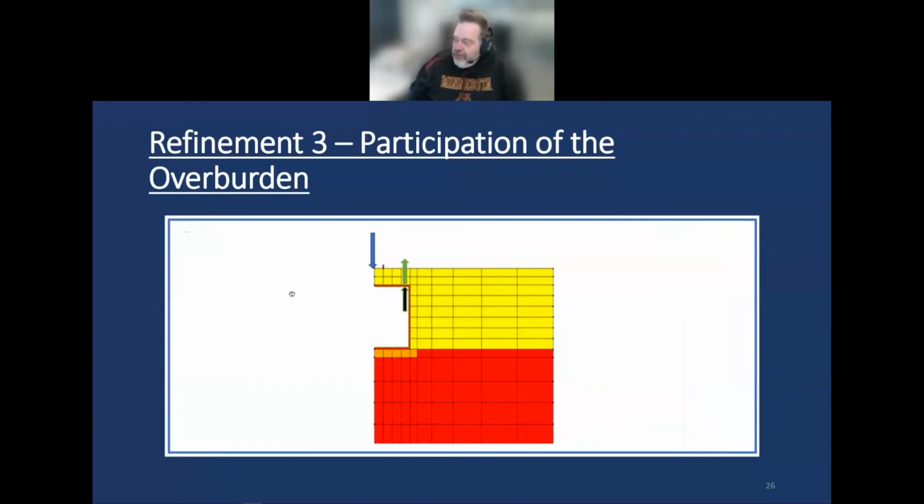Basically we did some models where we put a single point load at the middle of the box culvert, and we saw how much thrust was produced at the top corner of the wall, and whatever didn't make it into thrust here was carried by the overburden around the box culvert itself. Longer spans with thin overburdens, there's not much benefit at all. You get to 6 feet of fill on an 8-foot box, and there's some substantial benefit to this refinement.